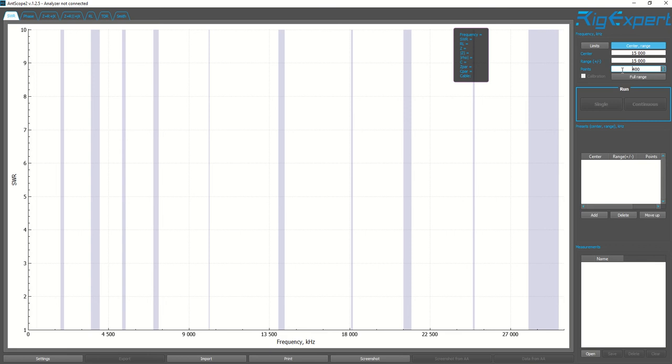So in this case, from left to right, I'm looking at 30 megahertz worth of bandwidth, right? So 400 points over 30 megahertz, the points are going to be spread apart quite a bit. And so you could do up to 1,000 points, and that would give you more points, but still plenty of distance between the points. Or you could do a smaller range, right? And so a smaller range, more points, gives you more fidelity of data, right? Better resolution of the data.